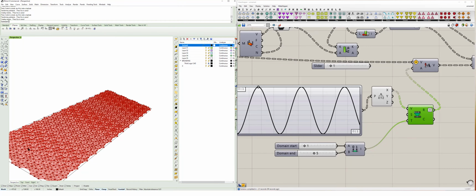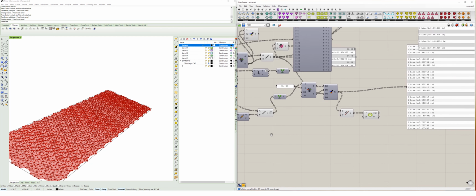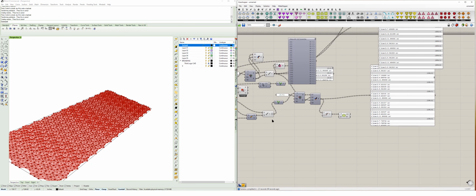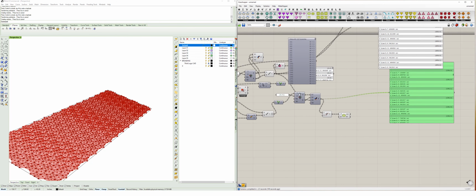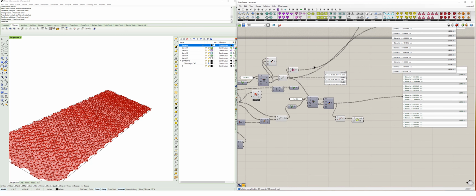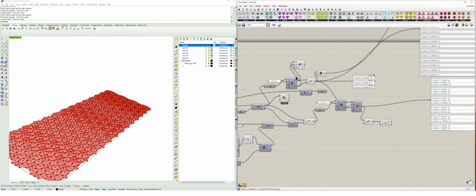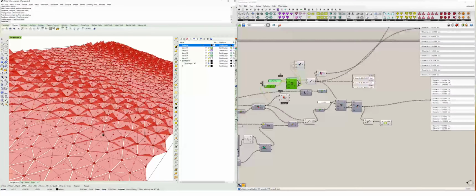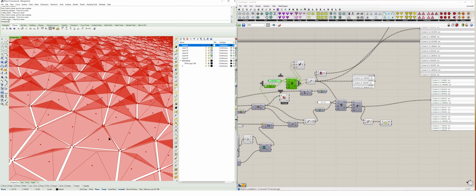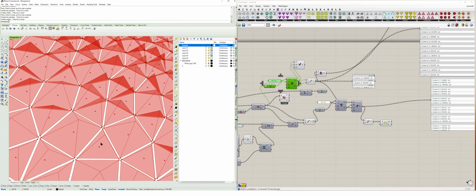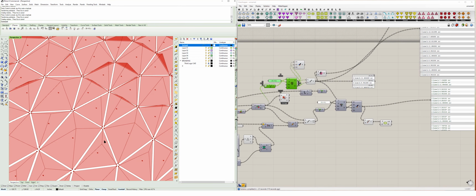All right, the final step we need to do is actually get this out. So we need to bake it and associate the colors to our geometry. So if you didn't catch the update from before, we offset our curve to create individual meshes, so that in this case for this space frame there's 1, 2, 3 meshes to create the entire panel.